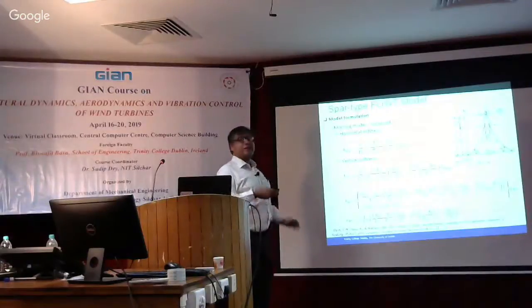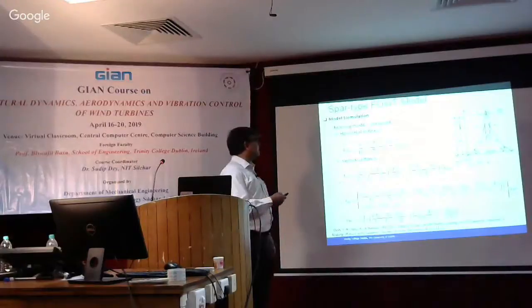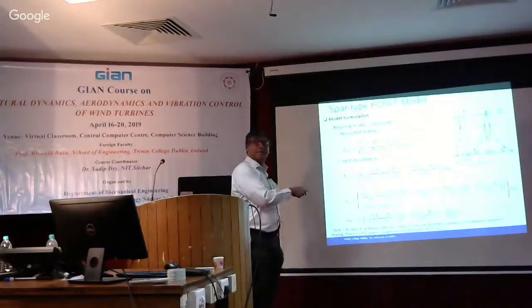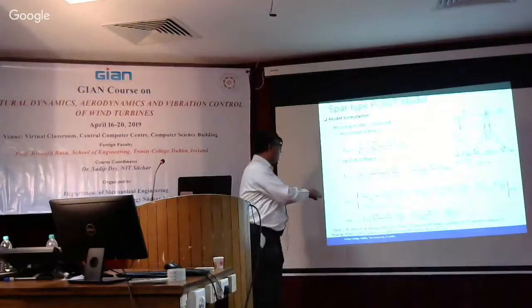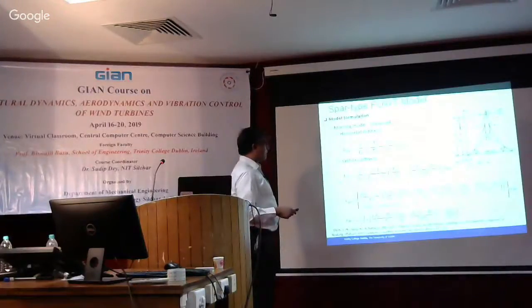But instead of going into all these details, if you have to design it in a simple way, you can use the horizontal stiffness and vertical stiffness. The expressions are given here. This is actually the roll stiffness here. And I think this title is missing here. Yeah. So there should be a roll stiffness here. This is the rotational stiffness. Just a small edit here. So if the stiffness term is horizontal, vertical, this is the roll stiffness. Is roll.